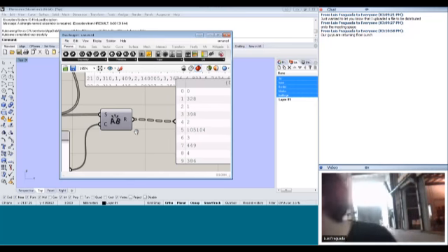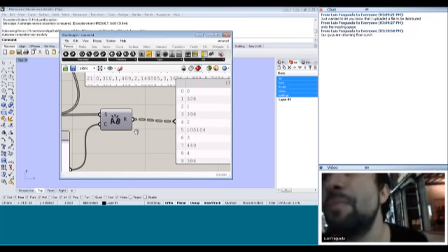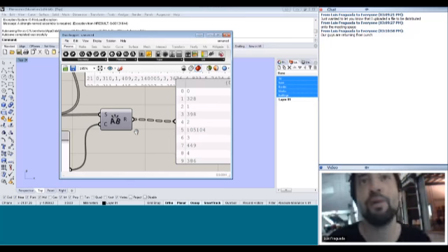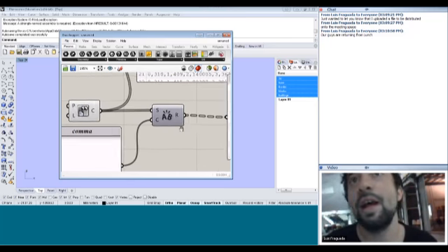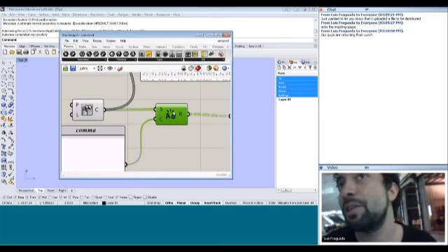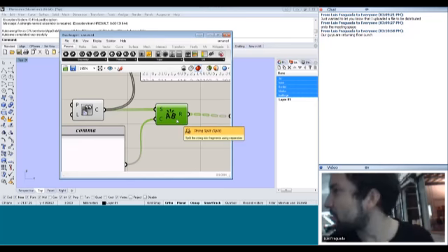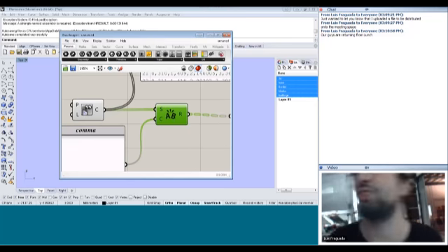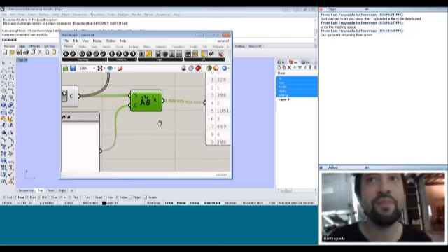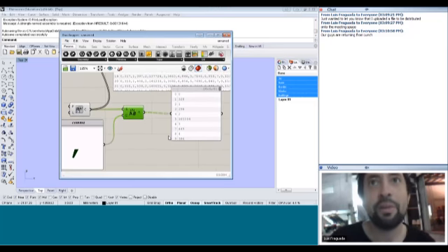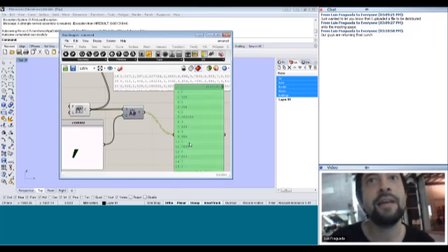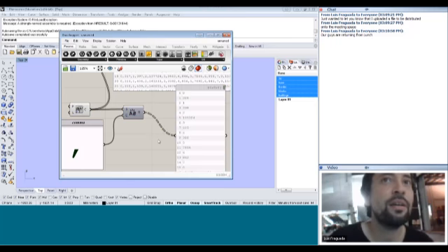There's nothing wrong, no. The question here was why this component in particular was dark gray, and it's because here we're just dealing with text, so there's no geometry or preview to show. That's why it's like this by default. But the most important thing we have to discuss now is that what we've created here is in Grasshopper what is termed a data tree, which is essentially a list of lists.